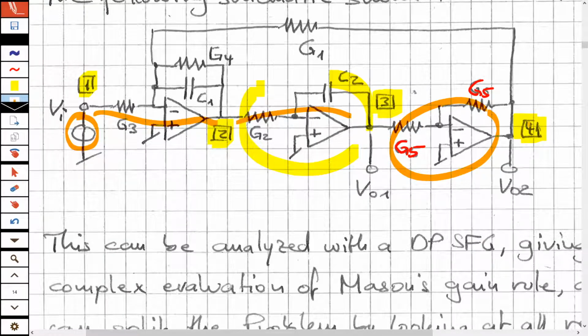That's the next one we have to do. That would be what happens if the output source is driven, and I want to know what happens in that direction. It is again the same type of circuit, so minus forward conductance divided by feedback conductance. So then I go from here to here, and maybe make this a little bit flatter. And then here I have the same feedback conductance, so let me copy paste.